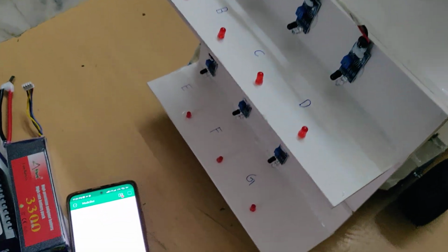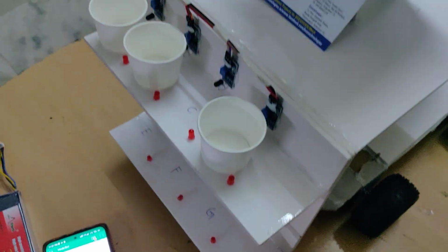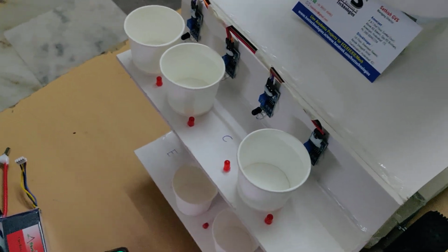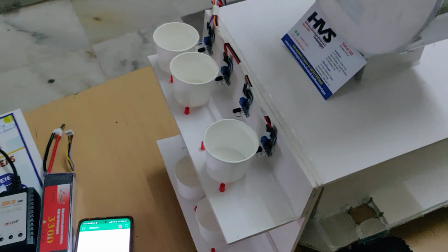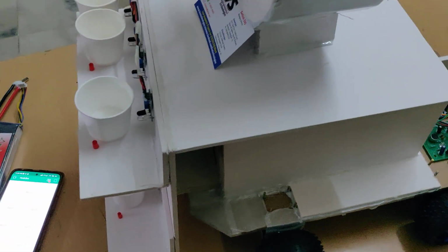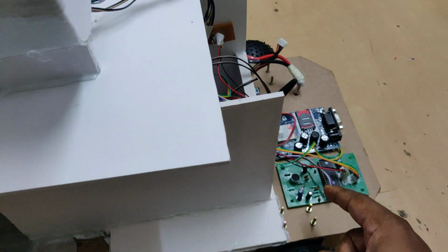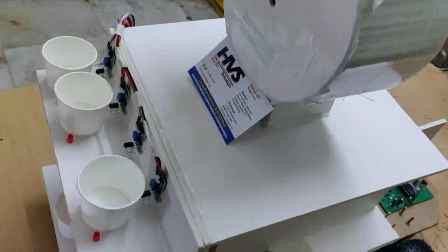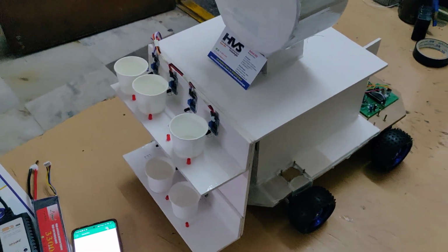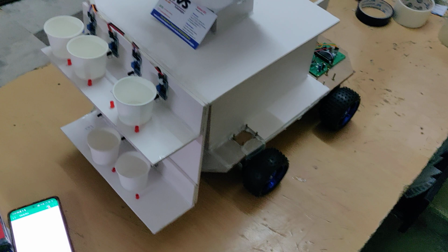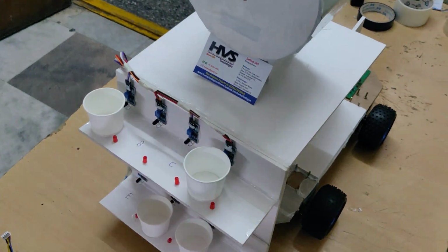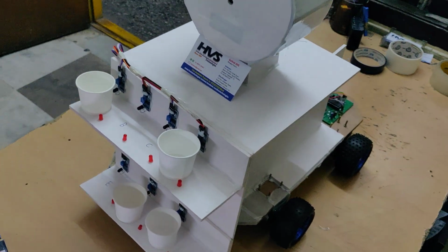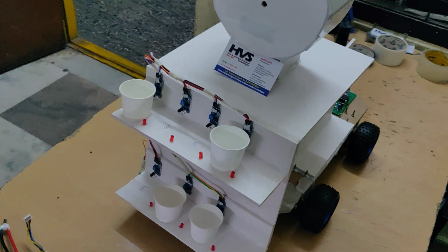Then when we place the respective medicines in front of the IR sensor, the IR sensor will inform the Mega board that there is a medicine to be delivered. It will announce a voice alert to the patient through this APR33A3 voice module. The speaker is placed inside this head, and it will announce the voice. Once the person hears the voice and comes and takes the medicine, that will be identified by the IR sensor, and it will inform the Arduino Mega that the medicine was delivered.